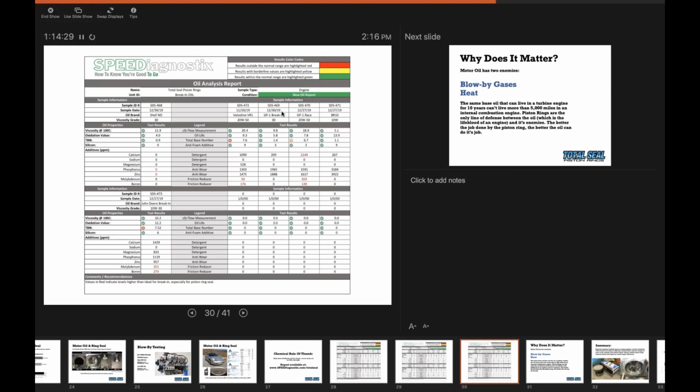So if you think of the three-piece oil ring as the gross or bulk oil control, the second ring is going to be your fine oil control. So we really like a Napier second ring. A ductile Napier second ring is a fantastic tool for helping oil control.